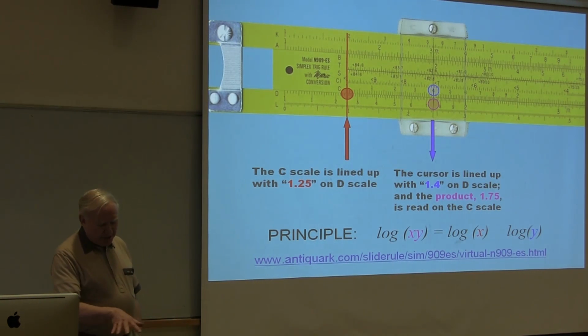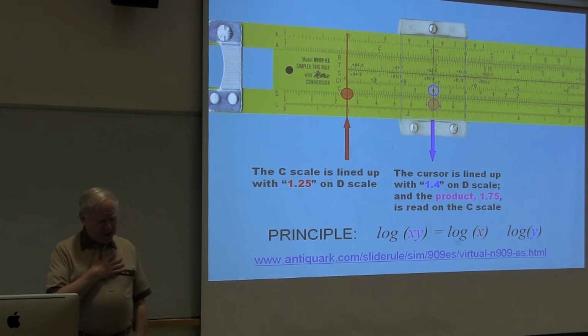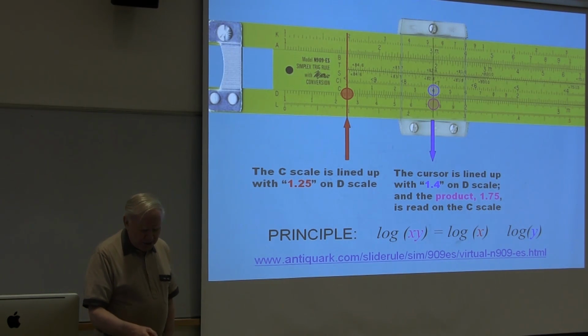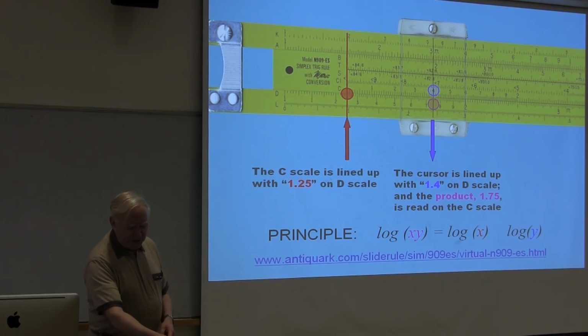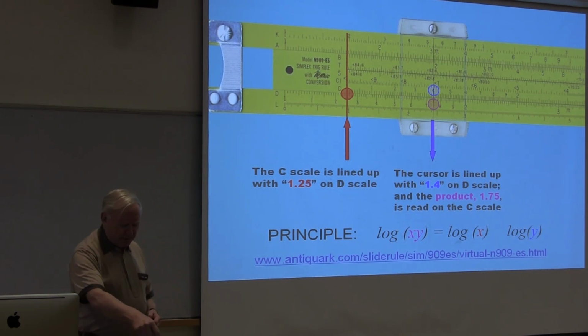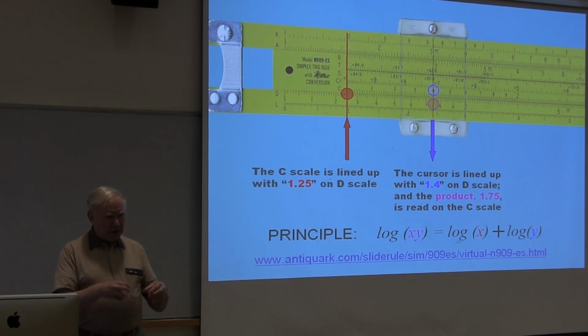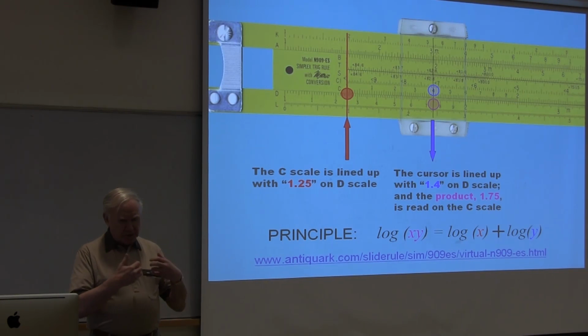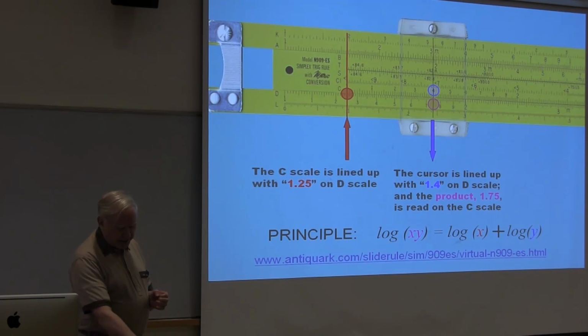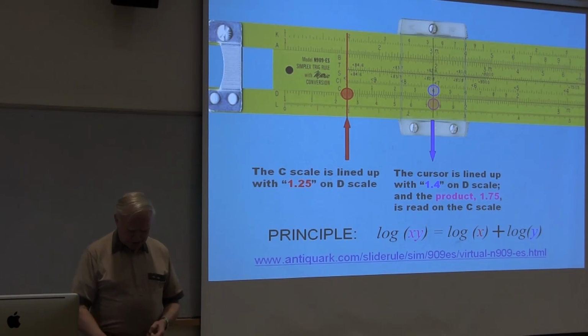Sorry. Here's how a slide rule works, in case you don't remember. You do remember what a slide rule is, don't you? I hope. Anyway, a slide rule is a little computing device, and you can multiply numbers. Basically, the idea is you divide up the scale into 2 logarithmic scales, you slide one against the other, and the sum of 2 logs can be read back, and instead of having to mess around with some kind of funny product, it's just a summation. Now, that idea is the principle behind a lot of modern analog circuits, this idea of using logs to do interesting things. Here, multiplication, but they can do many other things as well. By the way, it's interesting, there is this website where you can play with this slide rule. You can actually move it up and down and do things with it.